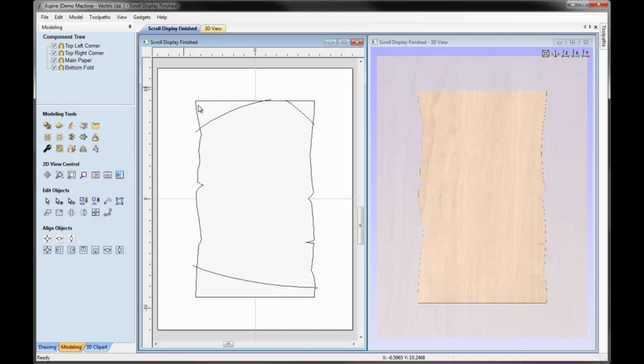Next I'm going to create the shape as if these folds were rolling over and up onto the main page again, and we'll then add that shape to each of those pieces that we just split off before we go ahead and mirror them and put them into their final position. To create that shape, I'm going to use the 2-rail sweep, and what I need to do is